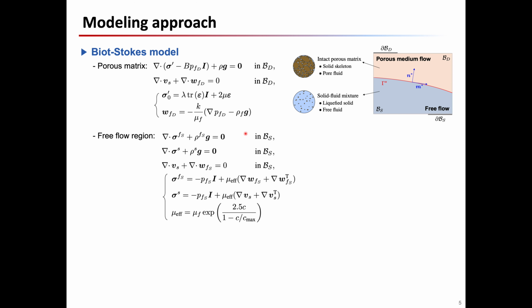On the other hand, the flow inside B_S is governed by the Stokes equation, where this sigma_FS indicates the fluid stress that depends on the pressure p_FS and the velocity w_FS. As shown here, we also assume that liquefied solid follows the same constitutive relationship as the free fluid, while we adopt the concept of effective viscosity that depends on the particle concentration C in order to replicate the suspension flow in B_S.